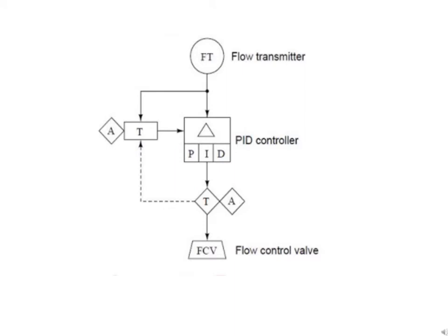Here we see a new type of line. A dashed line is used instead of solid. This has meaning in the world of SAMA diagrams. Solid lines represent analog signals such as process variable, set point, and manipulated variable. Dashed lines represent discrete on-off signals. In this case, the auto manual state of the controller commanding the PID algorithm to get its set point from either the operator's input or the process variable input.